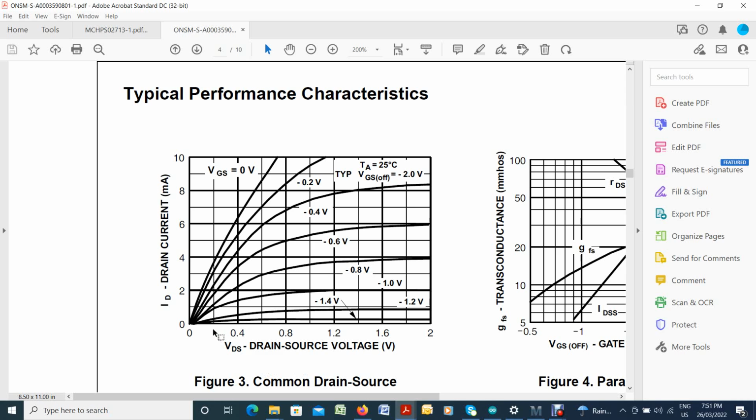But for the most part, in that circuit that I showed you, yeah, I even measured it. Although it's not exactly documented on video, the drain to source voltage is pretty low. It's in here. It's in this region. So this is how the JFET is used as a voltage controlled resistor in a feedback loop, to control the gain and stabilize the gain output of the oscillator.